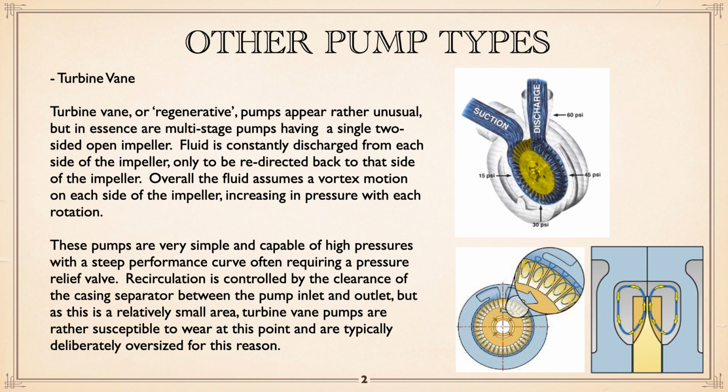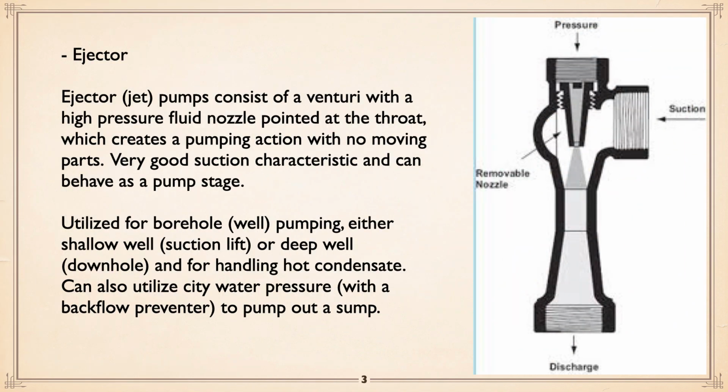But there they are. An ejector is a pump that isn't. Basically, if you have high pressure coming into an ejector, as you can see in the view, that creates a drop in pressure because it's pushing fluid down, which draws fluid in. So essentially, it acts like a pump. You have water coming in, but it'll move much more water through the suction and discharge.